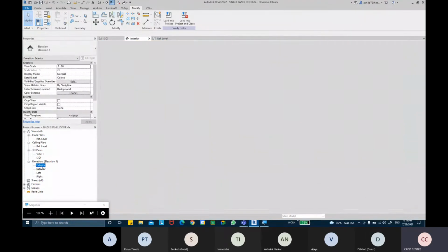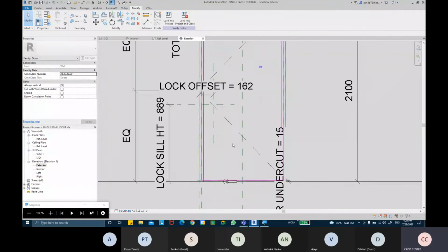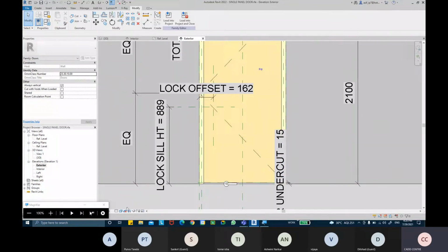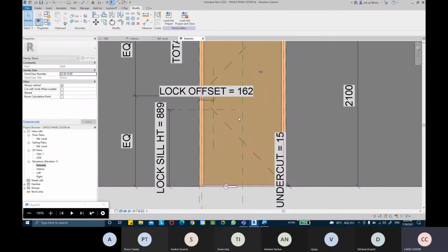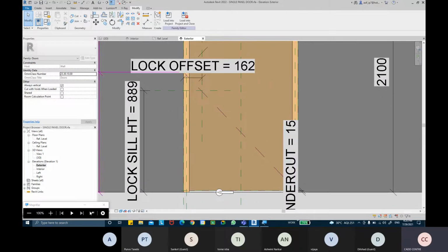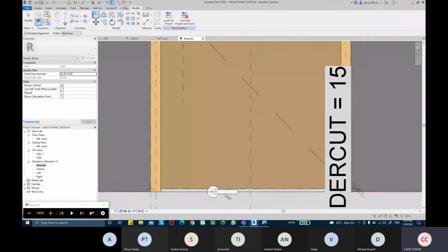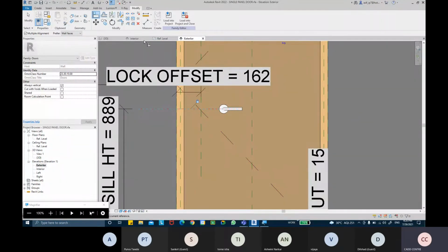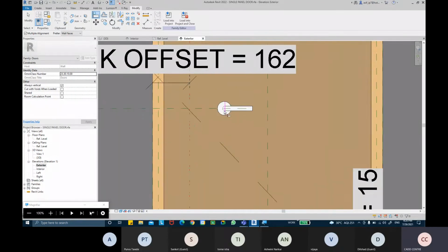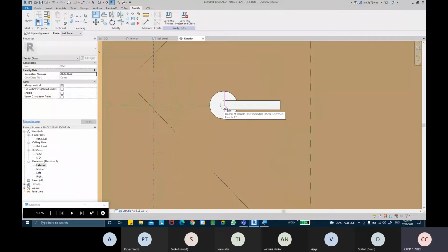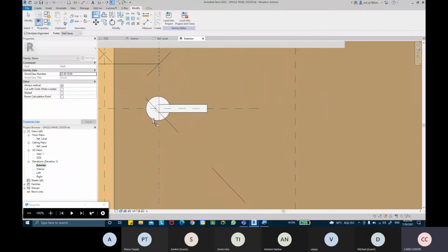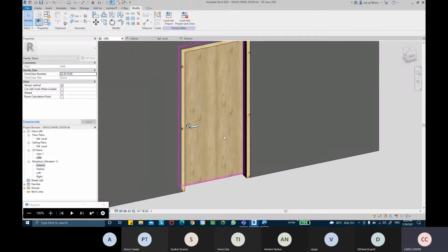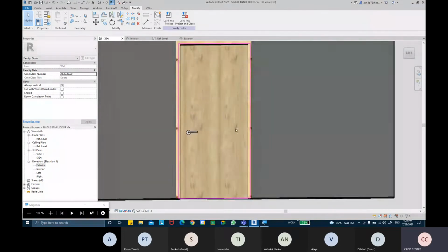Similarly on the other side, the exterior side, shade it, or you can use instant colors, and align it. Take the align tool, horizontal plane, horizontal sketch line, don't forget to lock it. The align tool, vertical one, also these vertical faces of that sketch model line, don't forget to lock them. So you get that door lever, then assign it.